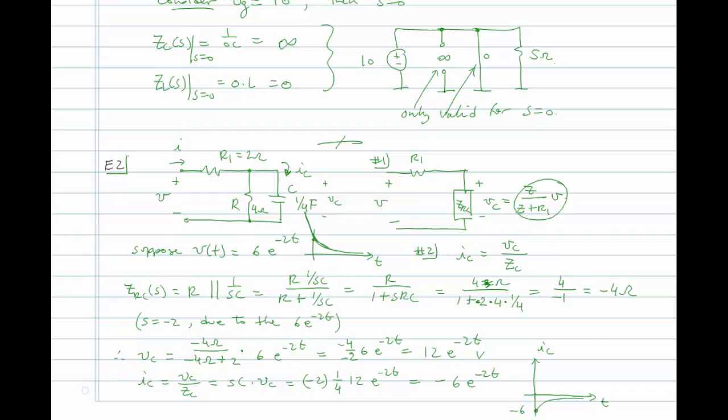That means that the capacitor voltage must have been greater as well and is now going down, because the solution here is that the capacitor current is negative, meaning that the voltage on the capacitor is decreasing exponentially. And that would make sense, since the input is decaying exponentially, and if the capacitor was at one point charged up and now it's being discharged by virtue of the input voltage V collapsing, then it would make sense that the current is flowing out of the capacitor and back toward the input voltage source V, and obviously through R as well.